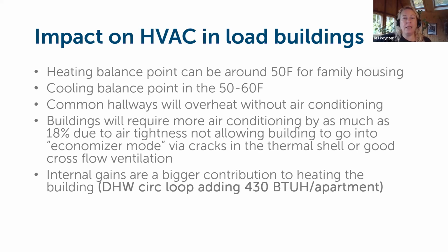On the flip side, because the buildings are so airtight and so well insulated, they hold all this waste heat that could be coming from lights, electronics, refrigerator. And what it's doing is it's pushing down the cooling balance point. So there is a positive impact from having super tight buildings. One is you don't end up having as much heating. The drawback is you end up needing more cooling.